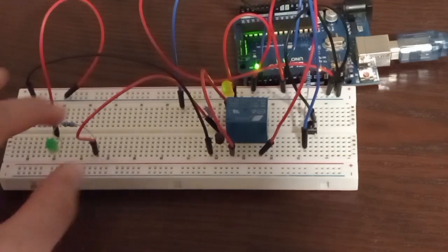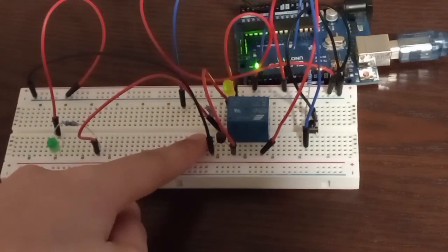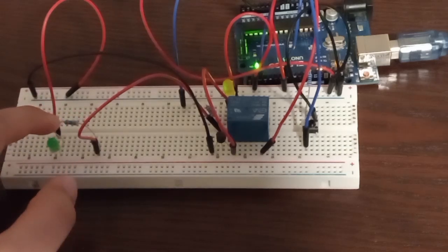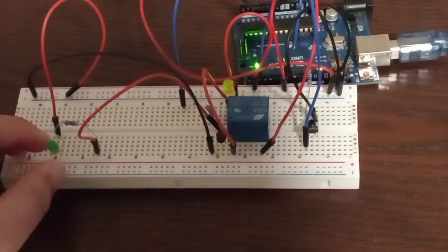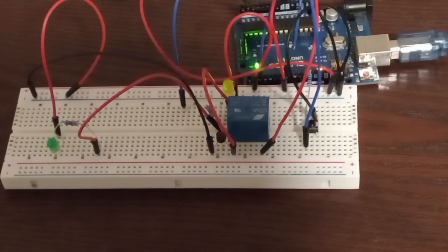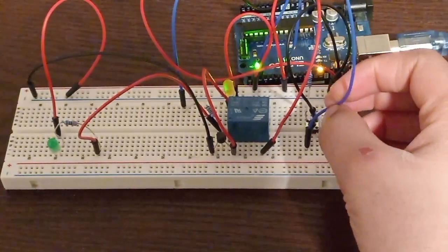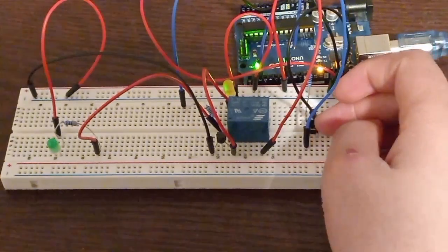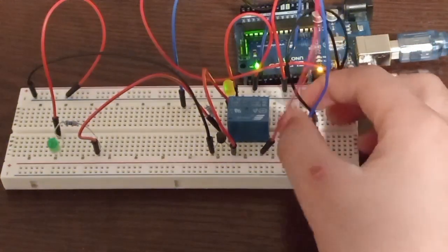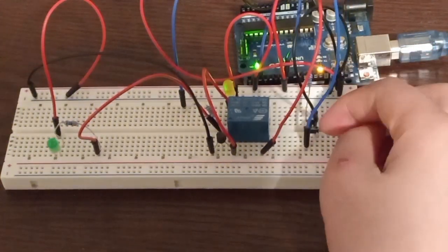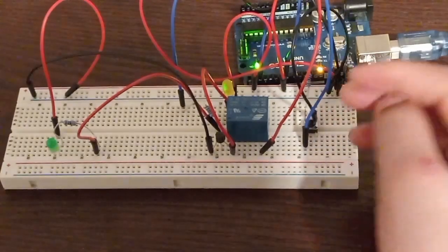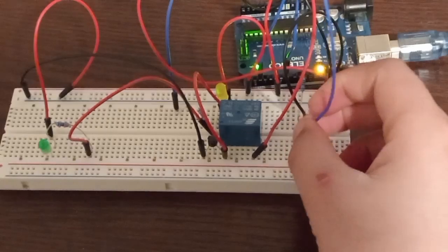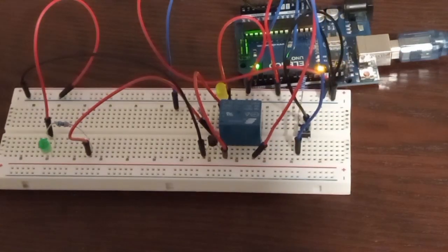This LED is connected to the common terminal of the 5-volt relay, and then it is connected through a 330 ohm resistor so that the LED can turn on. The push button has a pull-up resistor connected to it so that it's on at all times, and then the other side is connected to ground, in which when I press the button there will be no current to flow through, and this is connected to a pin, which is reading this information.